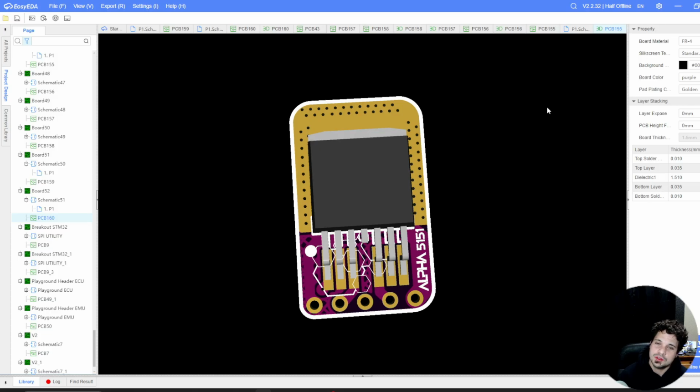So when the ECU says VTEC should turn on, it takes one of those wires, whatever you set in your software, let's say it's the power steering wire. It takes that wire and it sends a high logic to it, meaning that it is a positive logic set to a certain threshold, and the relay will see that all of a sudden it gets a high logic on that wire, a 1. That makes the relay turn on and allow power to flow from the 12 volt side on the input to the 12 volt side on the output to your solenoid. It's really quite simple.